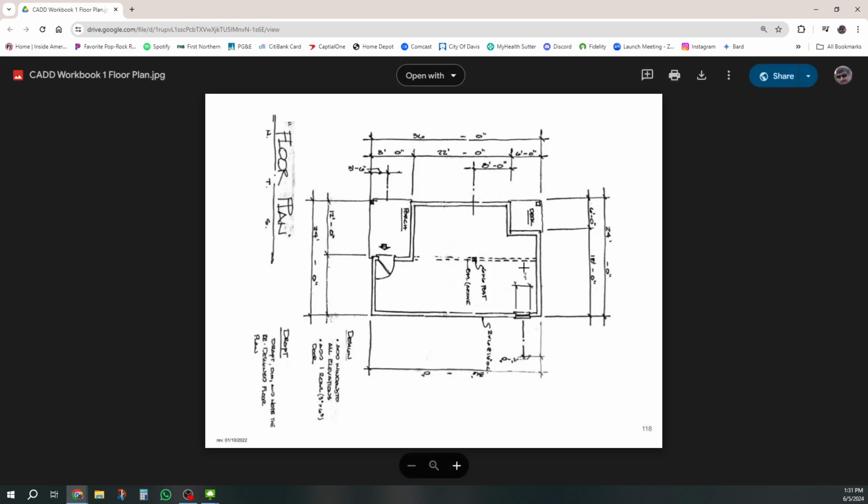There's a specific order. Okay, so windows and doors are the innermost line of the dimensions. Then come the exterior walls. Then comes the overall. And notice this is different than mechanical. Architects put a dimension on just about every single one of these. And they have the same dimension down here as they see up here. Okay, that is how architects do it. Mechanical people don't do it that way, but this is an architectural drawing. This should actually have a 12 on it also.